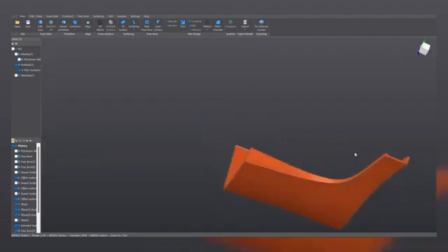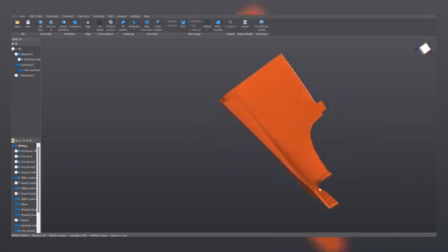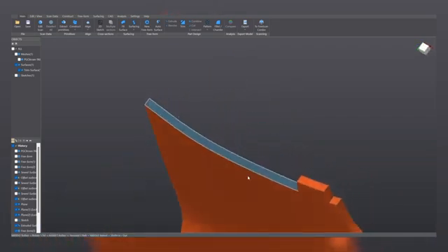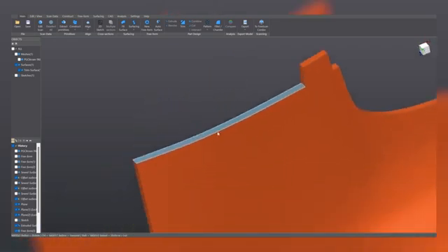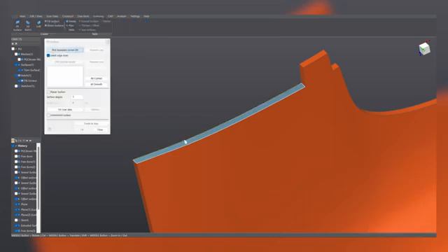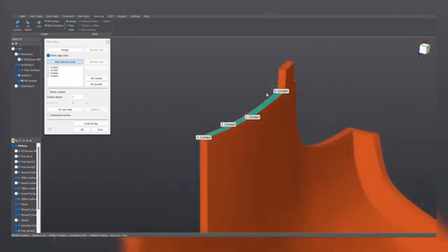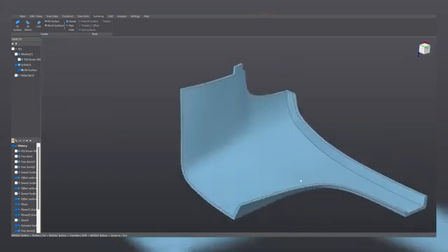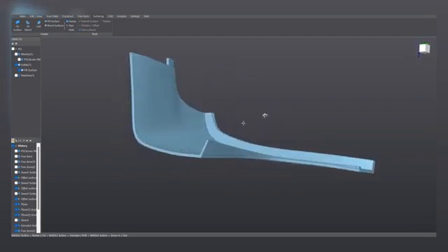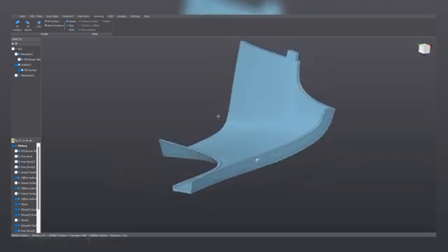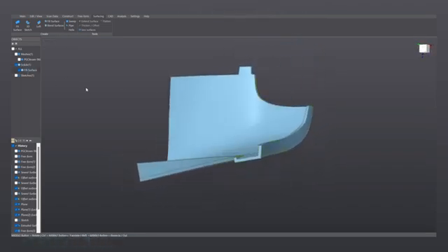And as you can see, we have all the surfaces stitching together, becoming the outer shell of our solid, except for this hole that has been left here on the top. And to solve it, we go to Surfacing, Fill Surface. We pick one of the boundaries, and the software automatically detects all the contacts of this surface. And as soon as I click on OK, and the surface is attached, the software recognizes that all these surfaces intersect with each other, enclosing an empty volume, and therefore it becomes, as you can see here, a solid.